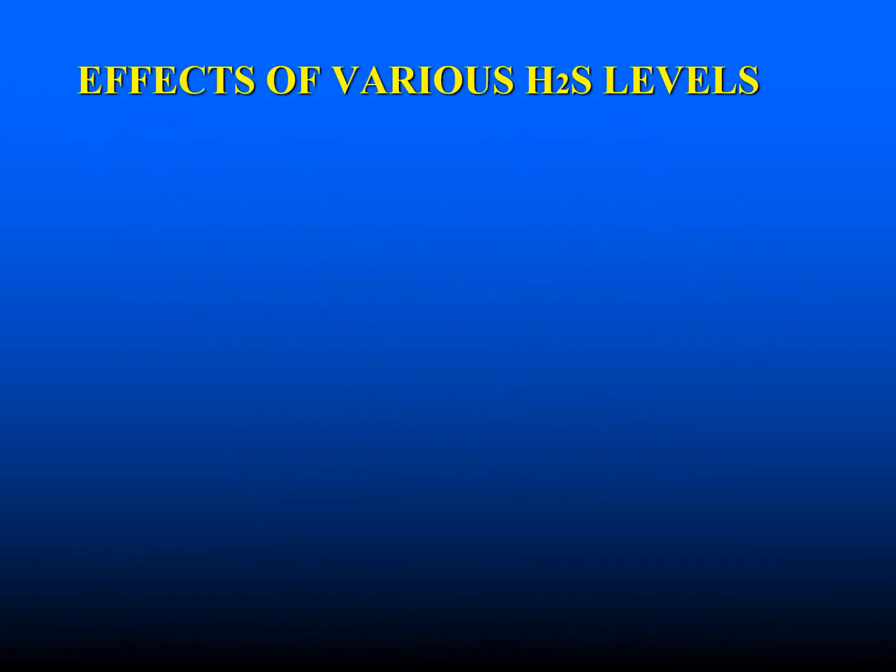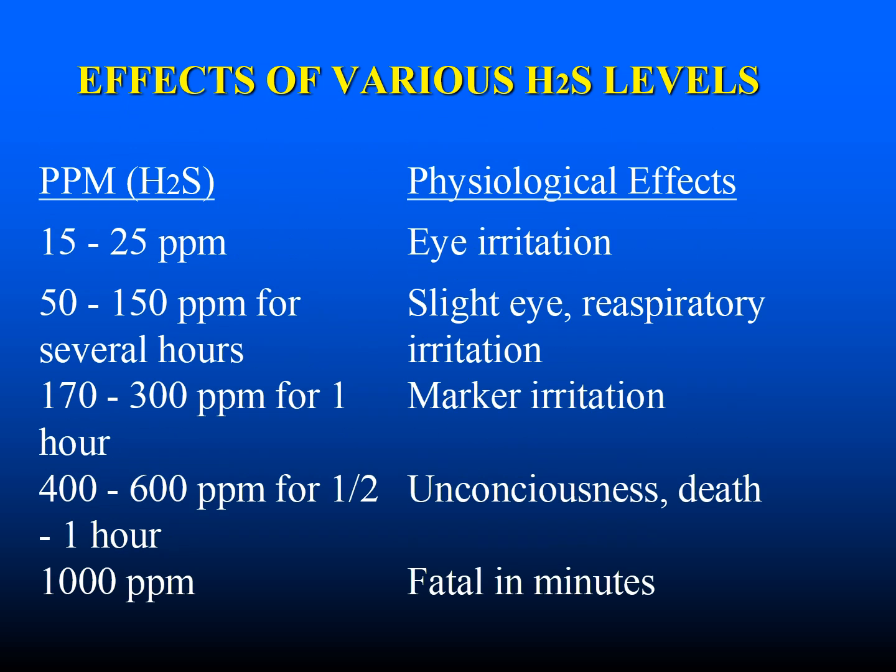Let's take a look at the various exposure levels of hydrogen sulfide. If the worker or the rescuer is exposed to 15 to 25 parts per million, it'll cause eye irritation. At 50 to 150 parts per million for several hours, they'll have slight eye or respiratory irritation.